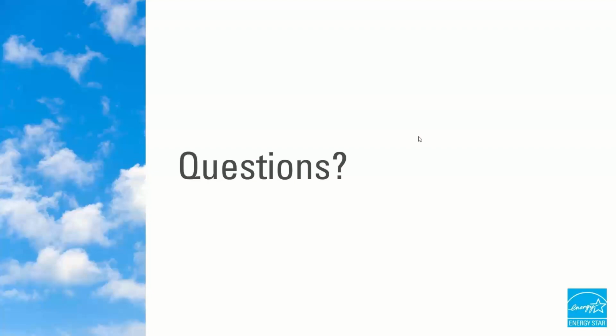For a builder that feels that they can incorporate a basic programmable thermostat, which could be as simple as a programmable schedule, they could still use a manual thermostat. They would just take a small ding on the Energy Star or on the ERI score, and they would compensate for that with something else. So generally, we haven't heard of many problems with that kind of level of control. We have heard some challenges with, say, variable speed heat pumps being controlled by a non-proprietary thermostat. And that's a different issue that isn't really directly impacted by the proposal here.